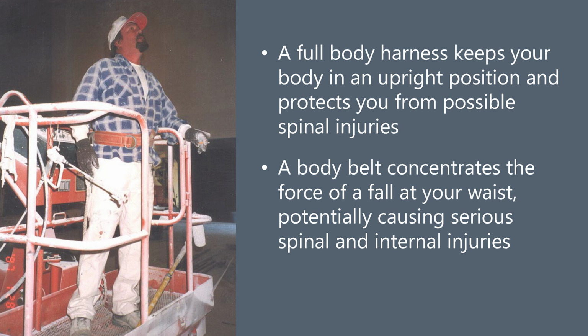Well, like right here, you have fall protection equipment built into the system, but this person here is wearing a body belt. Why is he wearing a body belt? Because what we're looking at is not a fall arrest system. It's more of a fall prevention, so that he doesn't fall out of the basket. There's YouTube videos where people do fall out of these baskets for one reason after another, and that's another story.